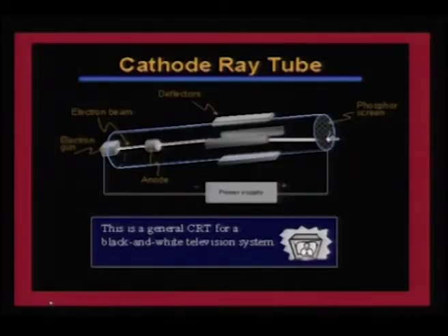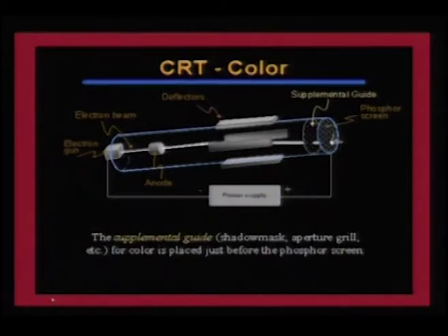So, when we look at the cathode ray tube, this is how the simple operation is. The electron gun actually brings out a cathode ray which is channelized through an anode. So, the direction is along this way. When it goes through this, you can actually deflect with a magnetic field, and based on the deflection you can scan this electron beam or bend this electron beam wherever you want. So, the cathode ray can actually hit the screen million times in a second as per the way the deflection is contoured. Now, we can do one more thing.